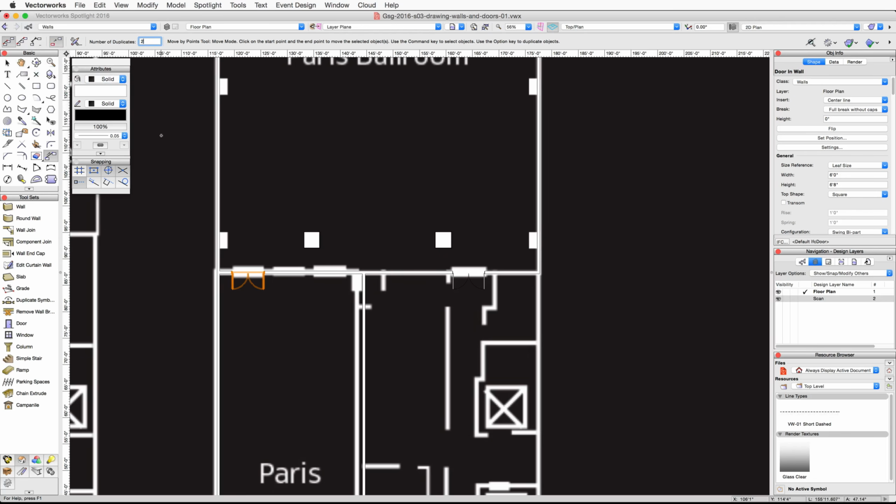Move your cursor over the center of the left bipart door we just placed. When the Insertion Point Smart Cursor cue appears, click once. Move your cursor to the right horizontally until you are in the middle of the next door. You can hold the Shift key to constrain the cursor horizontally. Click once more. This will place 2 more doors evenly spaced in the wall. Place 2 more swing bipart doors in the bottom wall of the Paris Foyer.